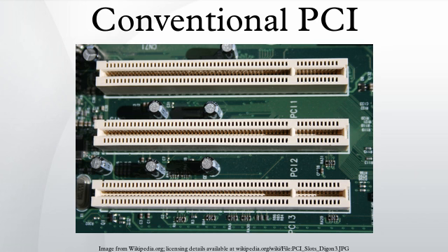Devices may have an onboard ROM containing executable code for x86 or PA-RISC processors, an Open Firmware driver, or an EFI driver. These are typically necessary for devices used during system startup, before device drivers are loaded by the operating system. In addition, there are PCI latency timers, a mechanism for PCI bus mastering devices to share the PCI bus fairly. Fair in this case means that devices will not use such a large portion of the available PCI bus bandwidth that other devices are not able to get needed work done. Note: this does not apply to PCI Express.